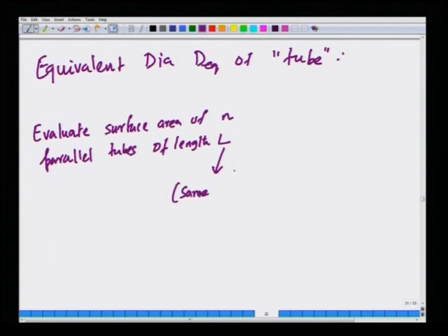which is a severe assumption, because in reality the actual length of flow of the fluid, since the tube is highly corrugated, should certainly be more than L, but we are assuming, because we do not know the length of the actual flow path of a fluid inside this corrugated space, the same as the length of the bed itself. So, this is an assumption.